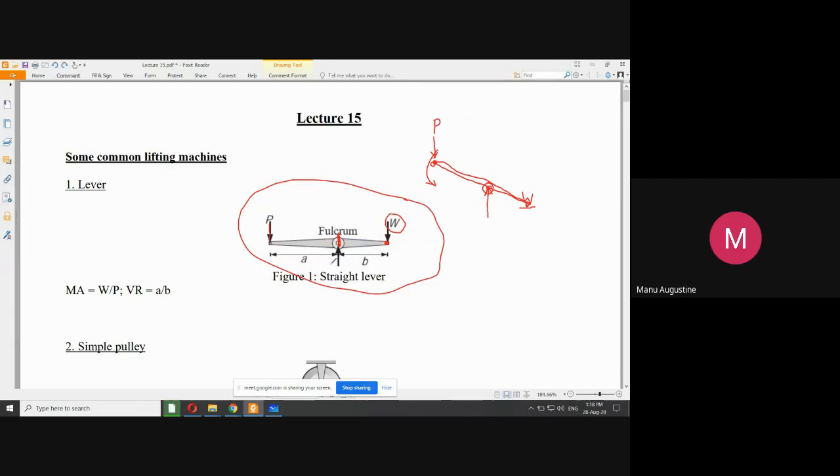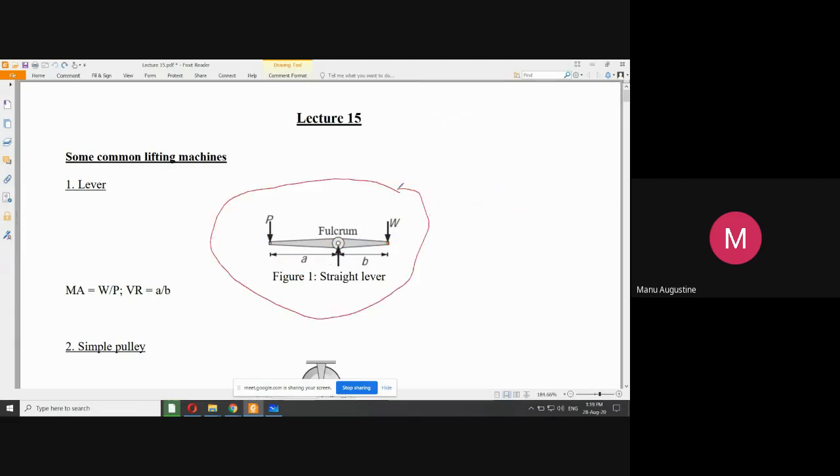So in this condition, we can say that since this whole system is held in equilibrium, if I take the moment of all the forces about any point, then the sum of all the moments must come equal to 0. This is a condition of equilibrium if you remember from your very early classes of engineering mechanics while we started the session.